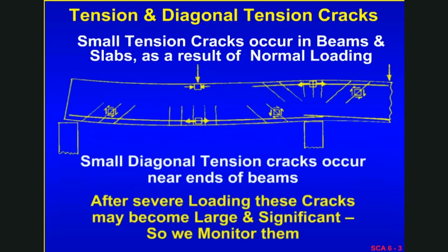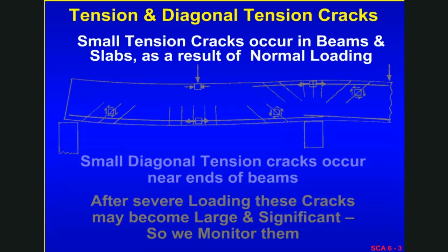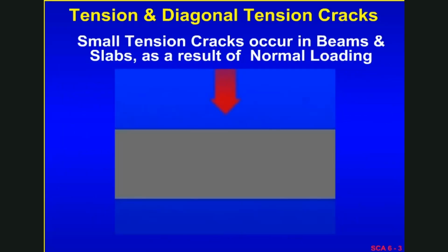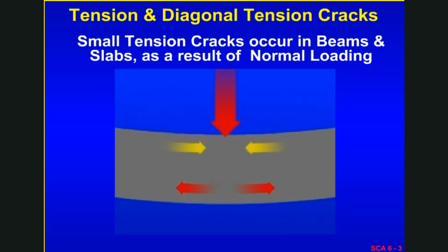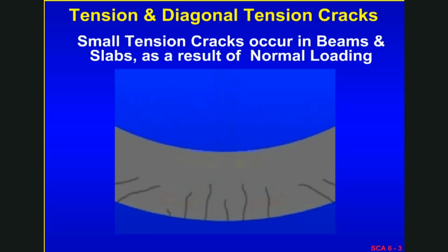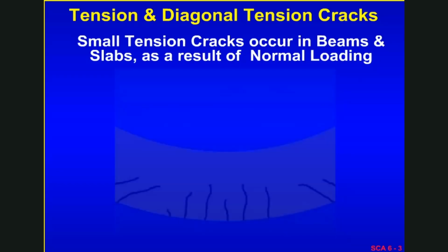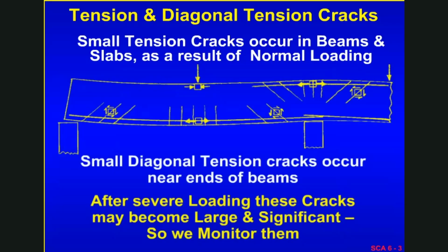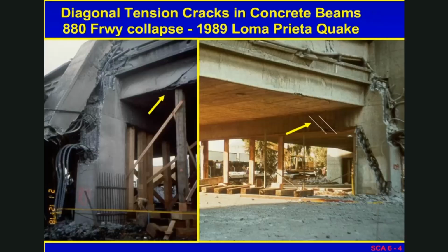And here's again the same kind of picture. The importance is if these cracks change. We know they're going to occur if the structure has been loaded severely. They really just indicate that it's working. But what we want to know during the rescue phase and recovery phase is, have they changed? Is the structure deteriorating? And is it a greater danger to us?